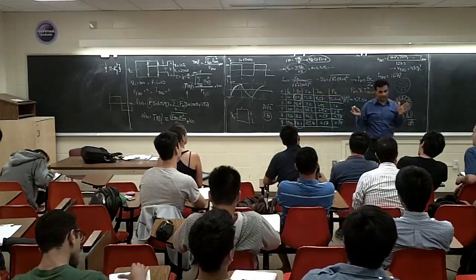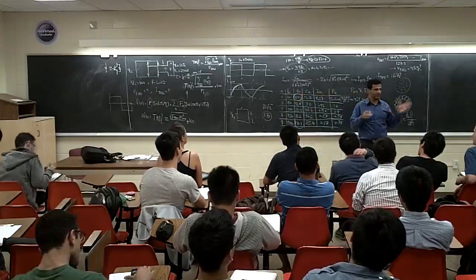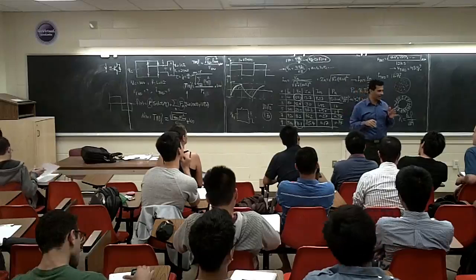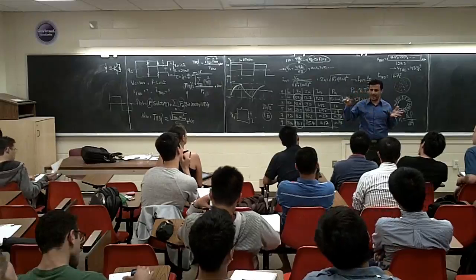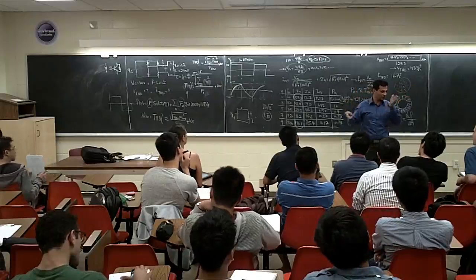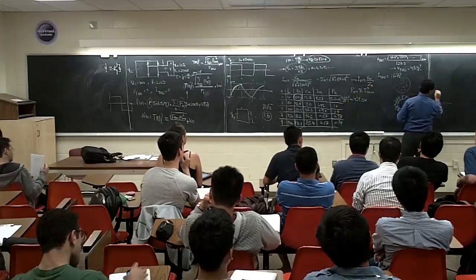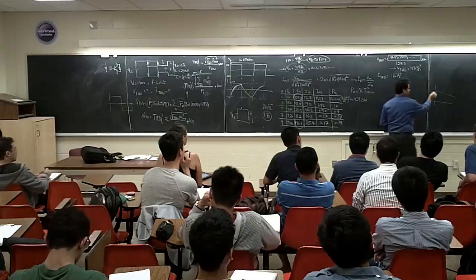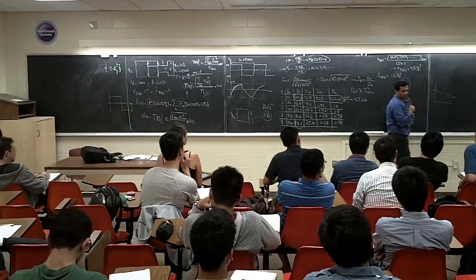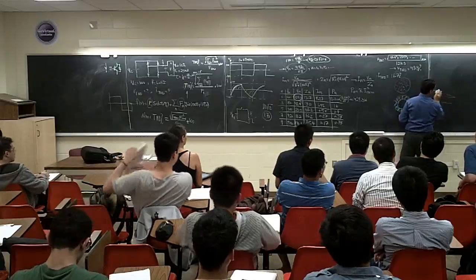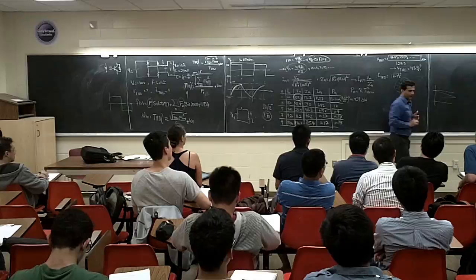This is the battery selection again. When you select the battery, if it's a lead acid battery, you can see it changes a lot. But if it's a lithium ion battery, it's pretty flat. If it's a flat battery, the charge and discharge doesn't change that much. This is a lead acid battery, this is a full charge, this is a full discharge. But if it's a lithium ion, if you start here, it's going to end up a little bit here, a little bit of drop.